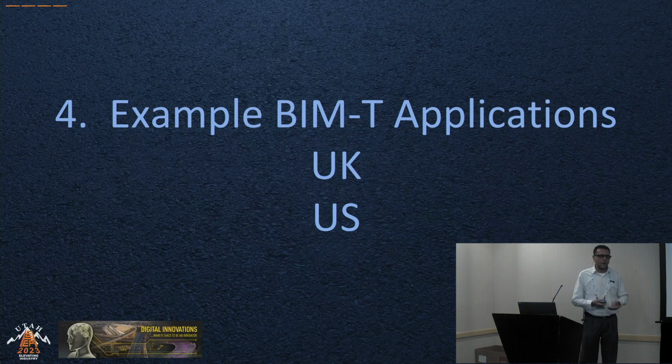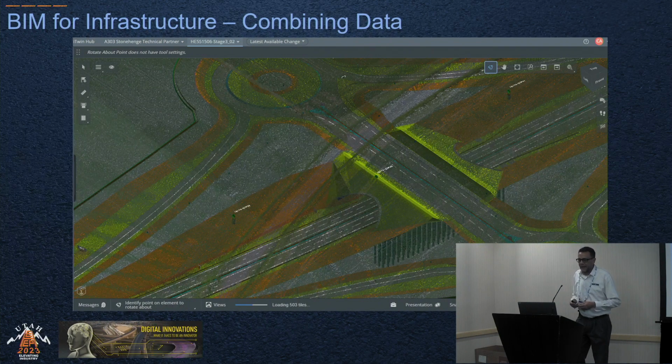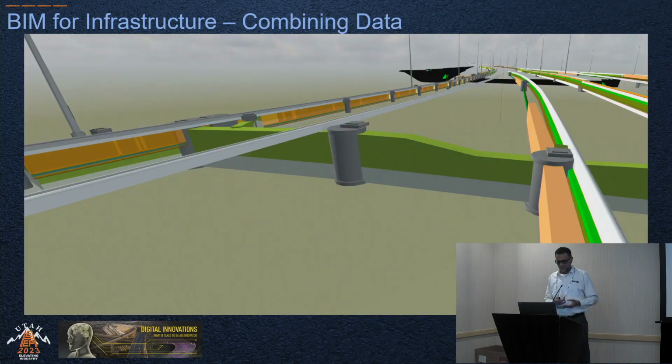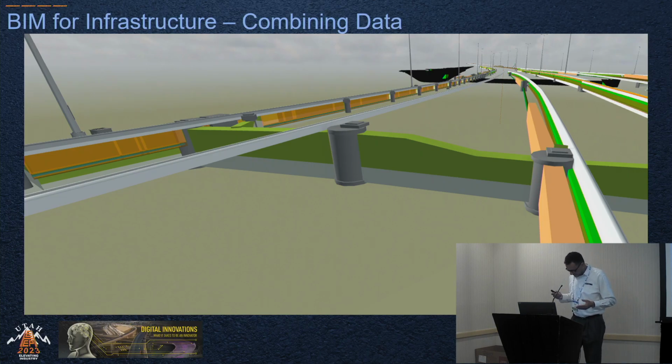So here's the example part. This is National Highways. And what you're looking at on the screen is an amalgamated model that was generated from GIS, the BIM design data, point cloud information, okay? You see all these layers that overlay on top of each other, but they all talk. They're shared. We had to model everything to LOD 300. So you see the entire network system here for just the pertinent aspects of the roadway system.